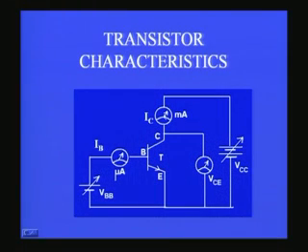So, you vary the voltage by using a knob, starting from 0 in some specific steps, for example 0.5 volts or so, and then find out what is the collector current for each of these voltages, and also record the VCE.